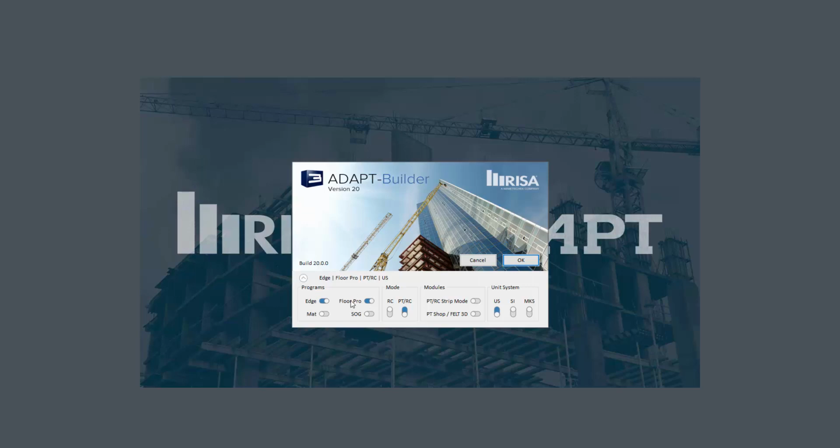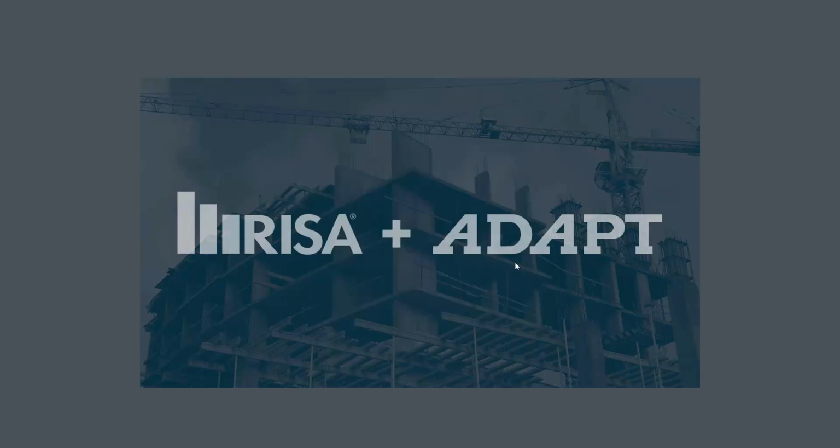So we want to use Floor Pro. This is primarily for elevated slabs with or without beams. We want to have the PTRC mode selected. This allows us to model the actions and essentially the objects representing post-tensioning cables. And then we're also going to look briefly at a difference between a single level run versus a multi-level run as it relates to post-tensioning. So these are the different options we'll be using in this tutorial.